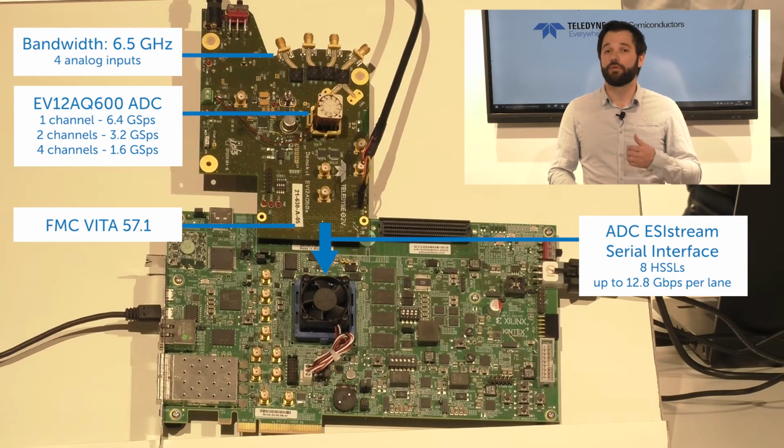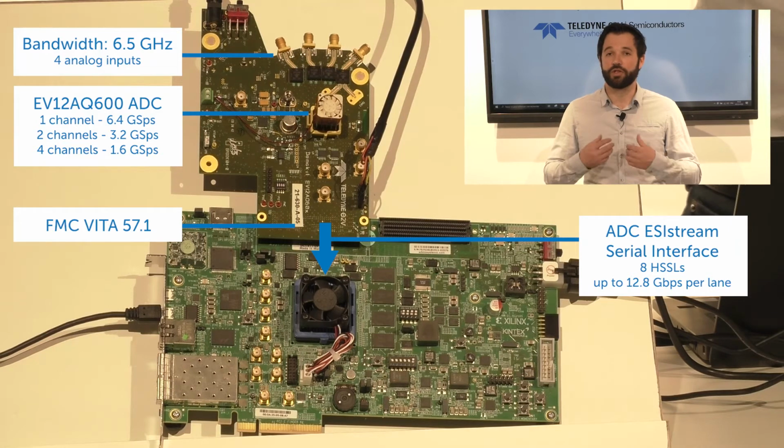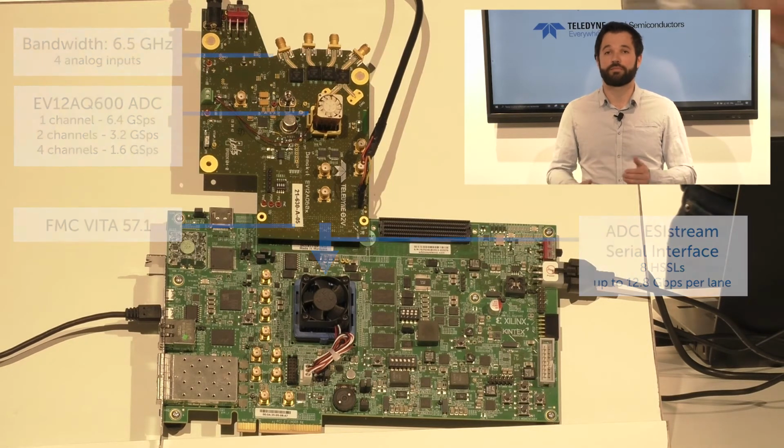So, using the AQ600 FMC board connected to a FPGA carrier board, you will learn how to program the FPGA and how to receive samples using a Python script, Vivado Hardware Manager, and Vivado Integrated Logic Analyzer. In this way, you can test that the ESIstream serial interface integration is working properly.